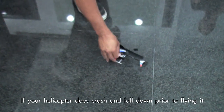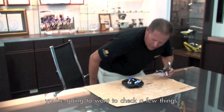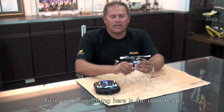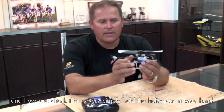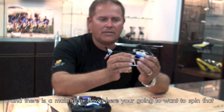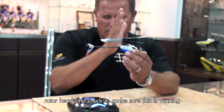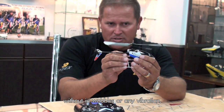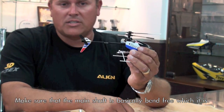If your helicopter does crash and fall down, prior to flying it, you're going to want to check a few things. First and important thing here is the rotor head. How you check that is very simply, you can hold the helicopter in your hand and there's a main gear down here. You're going to want to spin that rotor head and check to make sure that it is running without any wobbles or any vibration. Make sure that that main shaft is basically bend free, which it is.